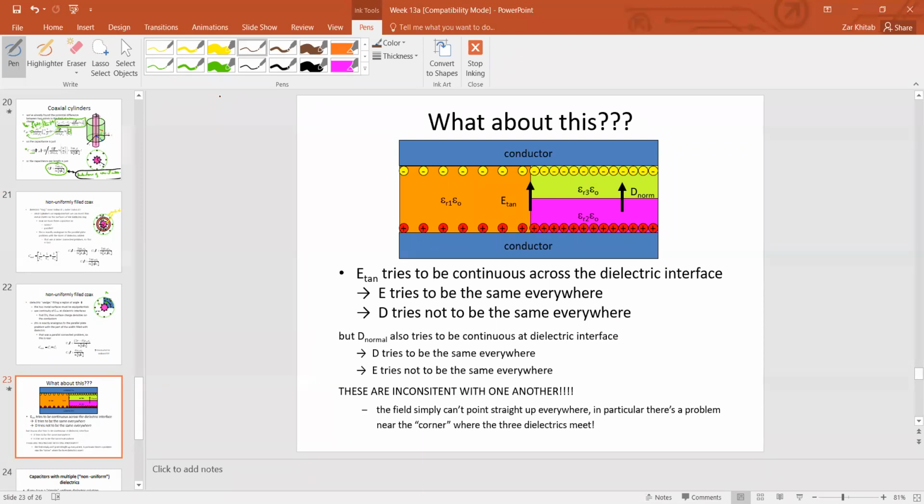You will never be able to calculate the capacitance of this structure precisely. It will be continuously changing. Why will it continuously change? Because by boundary conditions, suppose Et1 shall be equal at the boundary to Et0 and shall be the same as this value Et2. But the problem is here again the normal component will change.